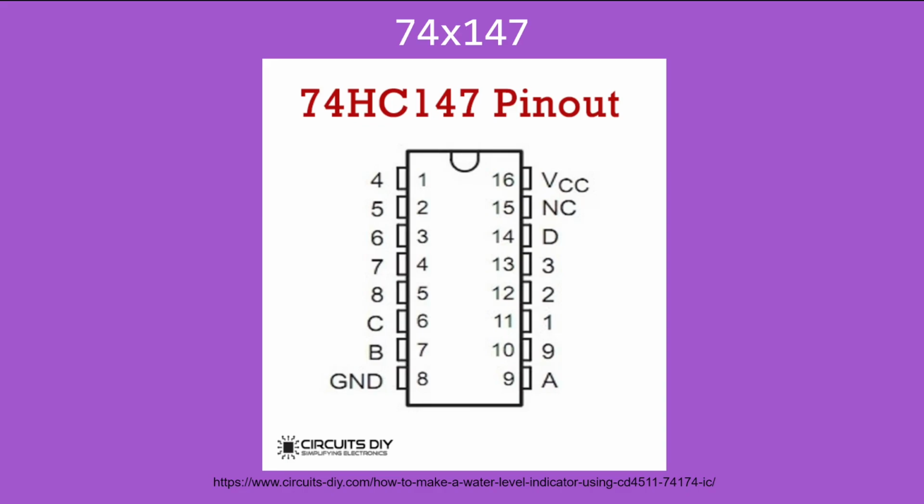Unfortunately, some of the pinouts are missing the fifth input line, and we're calling that non-connected. I think that propagated from one particular website which otherwise has great graphics, but I digress. So 1 through 8 are the inputs, A, B, C, D are the outputs. We've got one non-connected pin, assuming this is not an error, VCC, and ground.